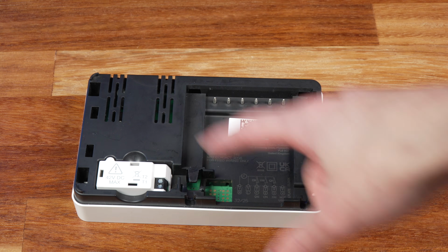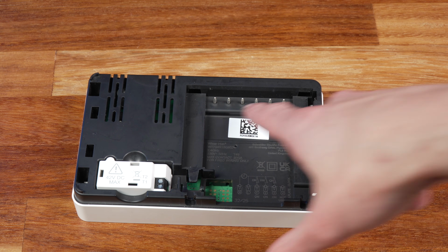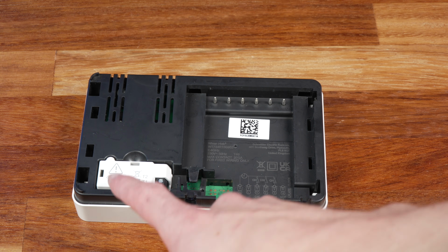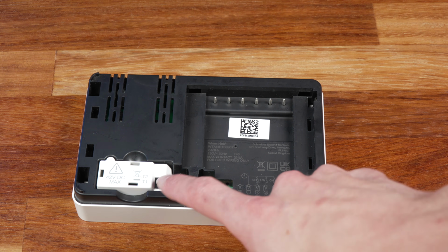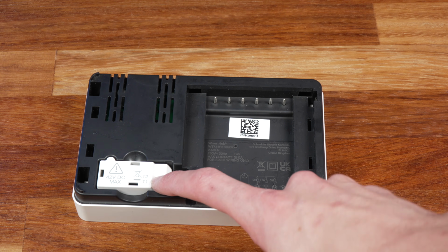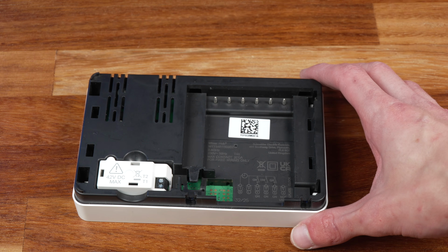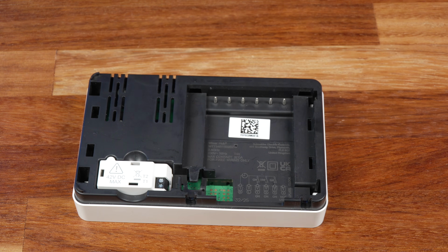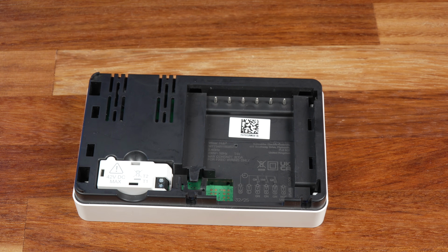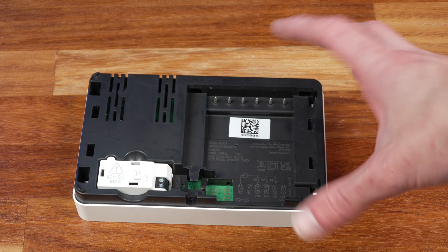So that was a run through of the wiring for the switch contacts that are on the back plate that connects these terminals here. But if you look on the back of your Wiser hub, you might also see this module here, labelled T1 and T2 with 42 volts DC maximum. And this is an OpenTherm module. I've talked about OpenTherm in videos before, and I'll be doing a dedicated video on using OpenTherm with Wiser, so we won't get into too much detail on this here, but essentially OpenTherm is a much smarter way to allow your thermostat to control your boiler.